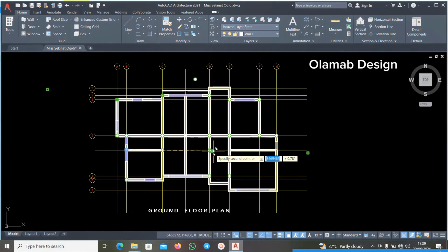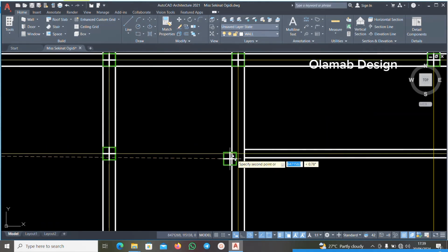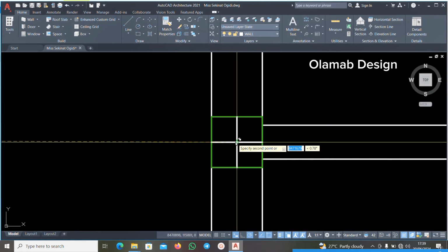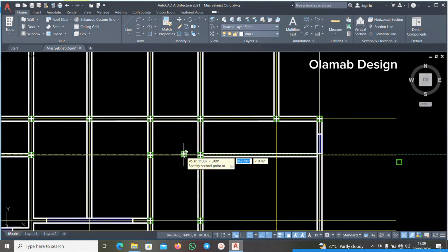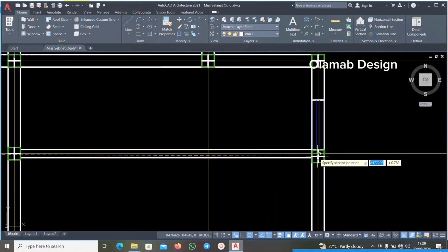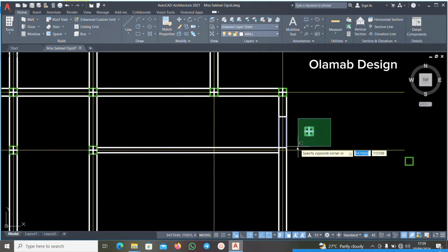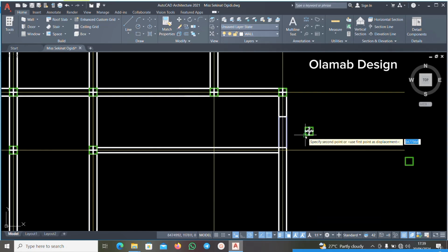You should know that it's because we have a grid line here that we can easily place our column at the center of this wall. And this grid line is now called a structural grid, and it is not an architectural grid anymore, because it doesn't have any usefulness in our architectural drawing. It is only useful on our structural elements.